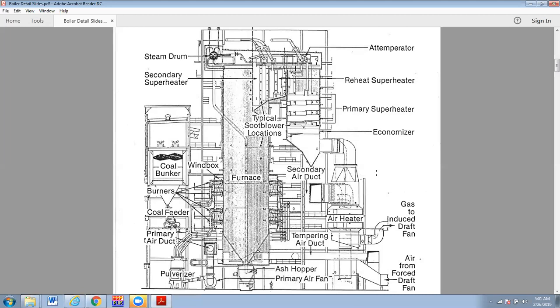Side of the boiler, and then from there it's blown out into the fireball where it is combusted. So that's one path. The air that does not get pulled off by the primary fan, part of it goes to feed the wind boxes, which supply additional air directly into the fireball. And then we have some air that goes to the secondary air duct that then is staged in further downstream